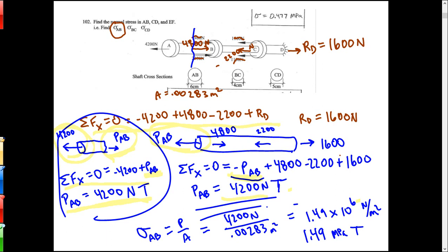You could even just ignore the positive and put left, right, or put arrows in your numbers when you're writing. You could, yeah. Right positive, left negative is just arbitrary. Somebody decided that long ago. But the important thing here is what goes into the equation depends on what direction you assume it acts. This acts to the left, so it went in as a negative. What comes out of the equation tells you whether that assumption is correct or not. They mean different things depending on whether you're going into the equation or coming out of it.